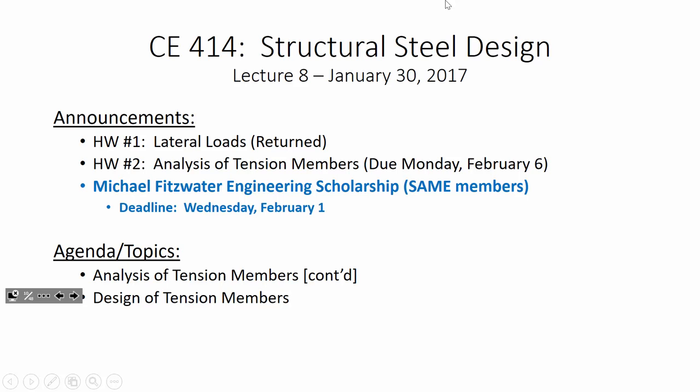One thing I will mention, I had a question earlier regarding shear lag factors for the angle. Make sure that you're referring to the right case. For instance, the one we did in class, we used case 2 and case 7. Well, case 7 is specifically for I-shaped sections, for W's, for M's, for HP's, for S's. Angles don't apply, so make sure you're using the right case. Everybody good?